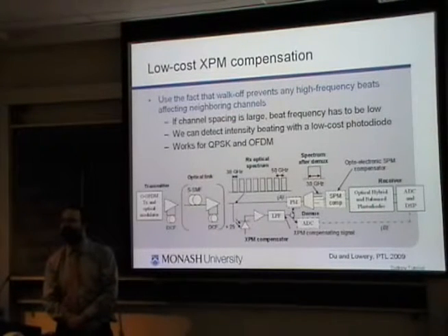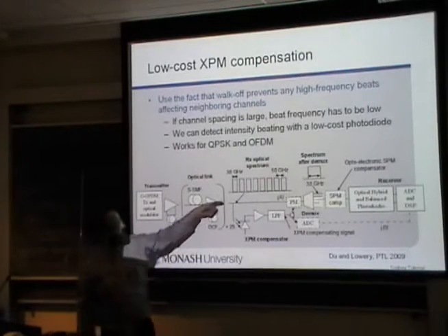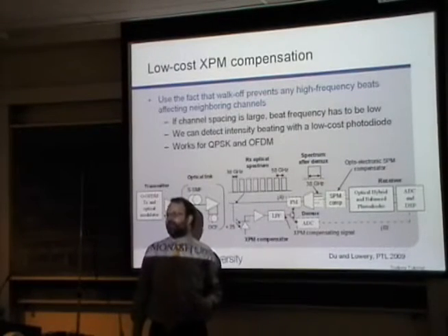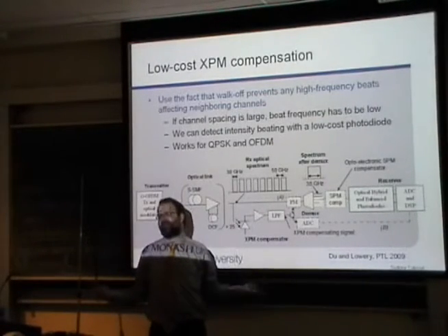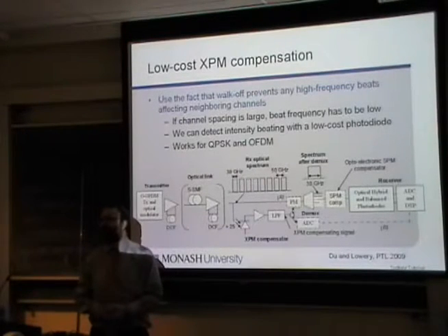How long is it? Do the lengths have to be the same? Do you have to synchronize the lengths? Yes, this path and this path must be synchronized, otherwise you're applying a waveform out of phase, or in phase actually, and so you would actually make the situation worse.